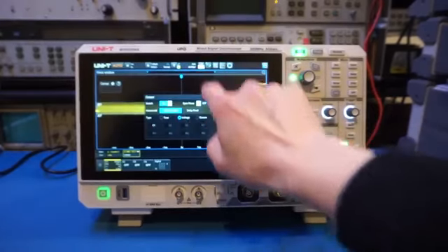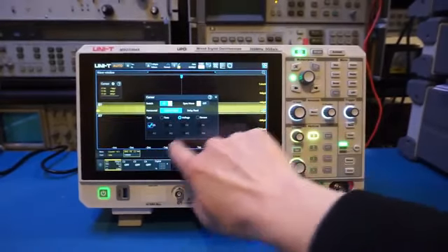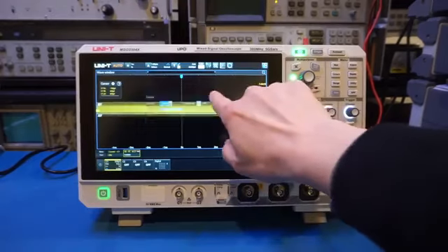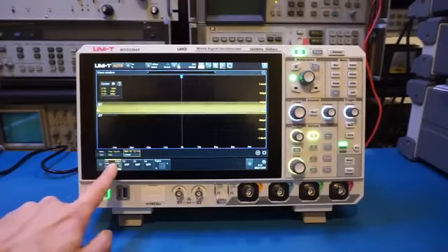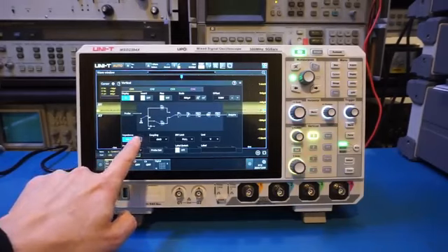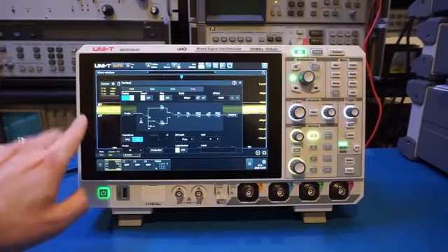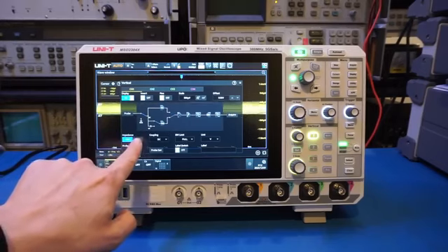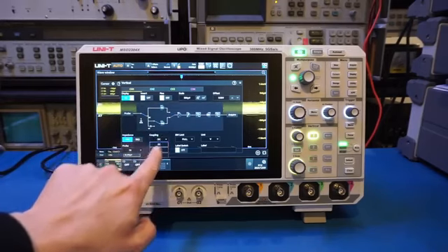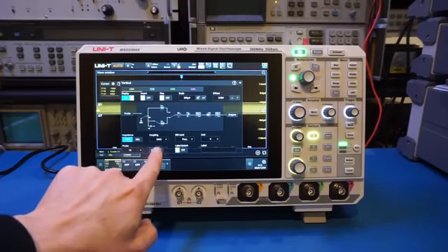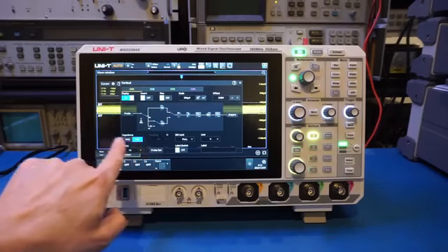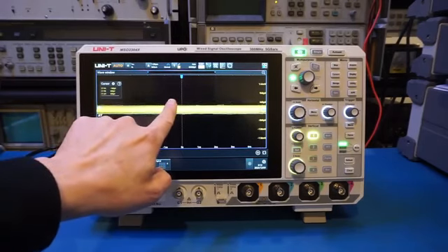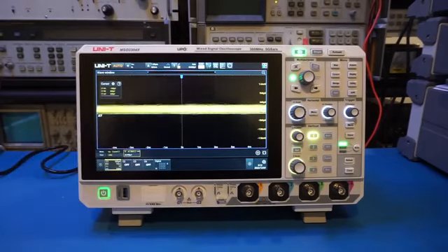And actually, let's go back to cursor. We apply it to channel 1. So the noise level is roughly at 1 division here. Let's see if we change channel 1 to 50 ohm. Does it change the noise level? Yeah, the noise level goes down a little bit. Okay, so that noise level was actually at 1 meg ohm. And with or without input, it looks similar. Yeah. So at 50 ohm, you can see the noise level is actually lower. It's at roughly 420 microvolts.